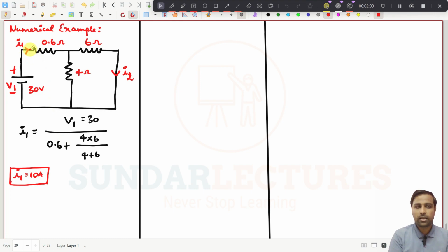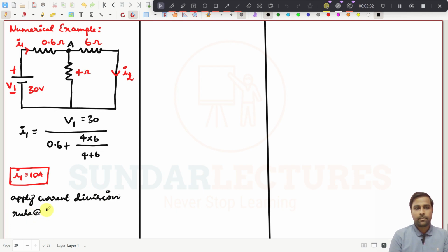Now you know this is 10 amperes, and if this 10 amperes is coming here, then apply the current division rule to get this current and this current. That is also very simple, right? Because this point, I'm just considering it to be A. So I'm just applying the current division rule. Any of these kind of things you would have already known, current division rule at point A.